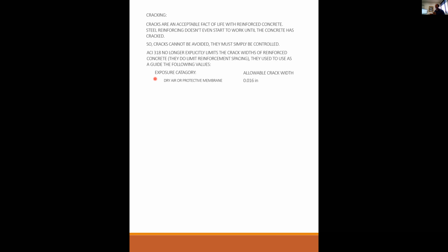I'm not even sure that's really a word, but that's what it says right here on this little piece of plastic. It says a crack comparator. And if I put my crack comparator on, say, the L's in the allowable right here, the thickness of the vertical line of the L in this allowable right there is 20 thousandths of an inch.